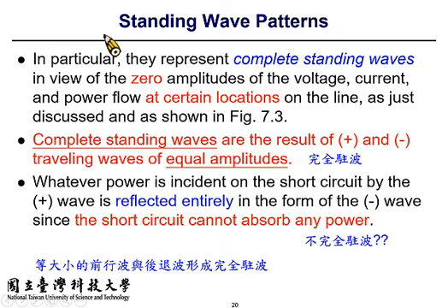So how about if you have a resistive load? Now, if you have a matching load, that is, you don't have impedance mismatch or impedance discontinuity on the transmission line, you will have no reflective signal. All the incident signal goes into the termination. In that case, if you have a matched load, you will see no standing wave. How about the case in between, between the matched load and the short circuit, open circuit?